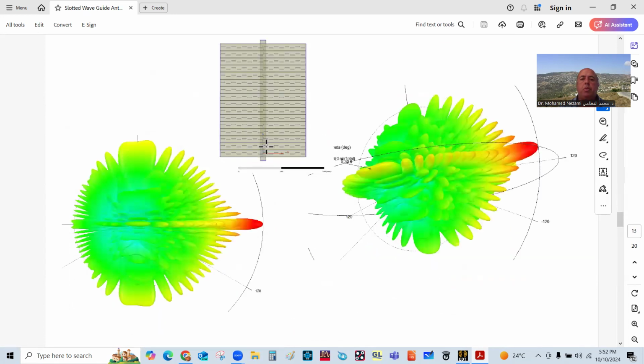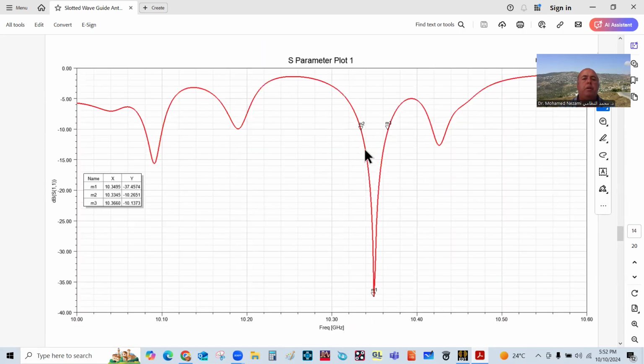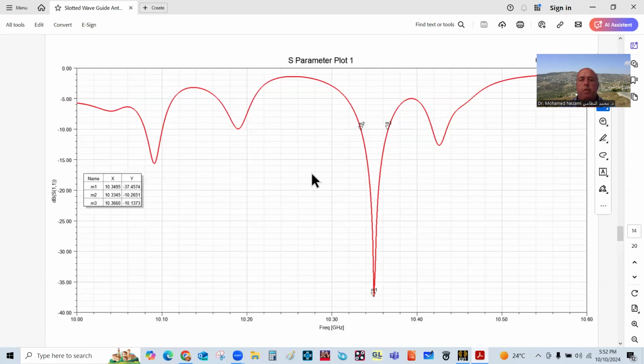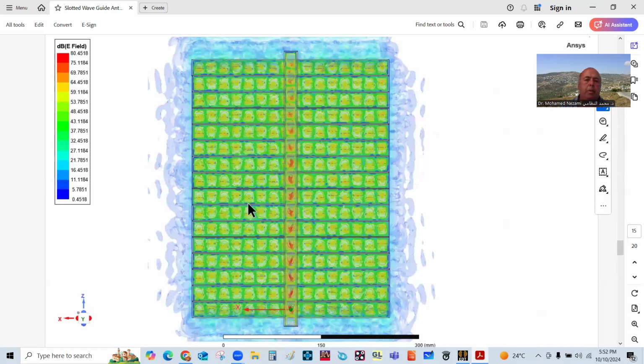And so that's what, okay, here is the beam. It looks very nice, a pencil beam. Now the return loss is pretty good, but you can see how narrow this band is. That's one of the disadvantages of this waveguide. That's why its usage has classically always been for radars and some other, few hundred megahertz, around my center frequency, of course, this was designed for 10.3 gigahertz.